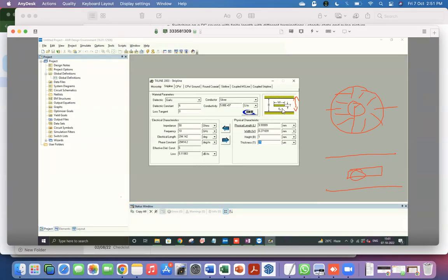And that's where the microstrip line, which I had introduced last time, and we'll look at it a little bit later today also, is convenient because you remove the top ground plane and the top dielectric, and then you have the center conductor exposed. So then it becomes easier to connect, even though not as easy as a third type of transmission line, which is the CPW transmission line, where both the ground plane and the center conductor are on the same surface. So then it's very easy to connect components across it. And it's actually quite a popular choice of transmission line because of that as well.